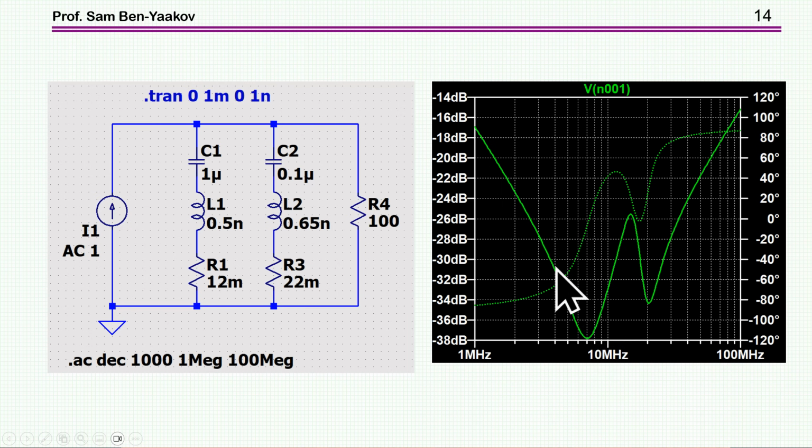This region above resonance, the capacitor is shorted, we are left with the inductor, and therefore this portion is inductive, and now the 0.1 microfarad kicks in. It's lowering the impedance, well, but not that much. Okay, it's lowering, no question about that here, as compared to this. This would have continued like this, so here we have an improvement, okay, but that's not a very big improvement. It is an improvement, especially around this frequency, but it's not what we sort of expected.